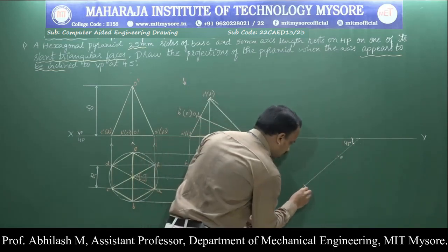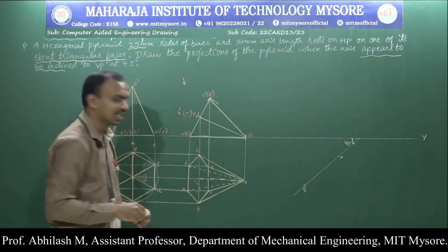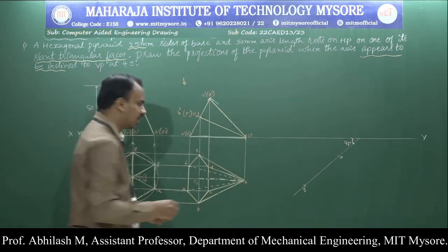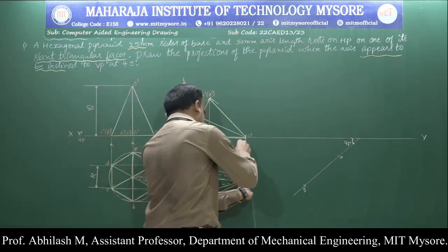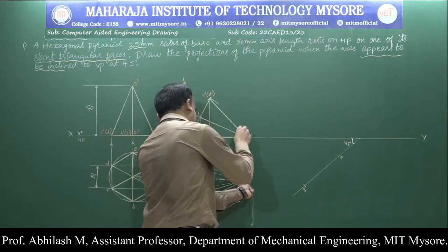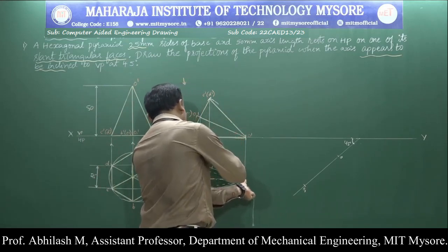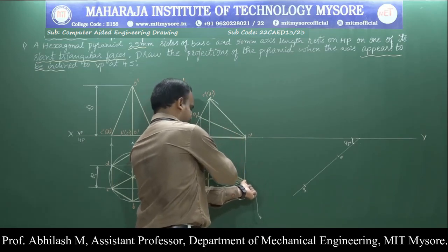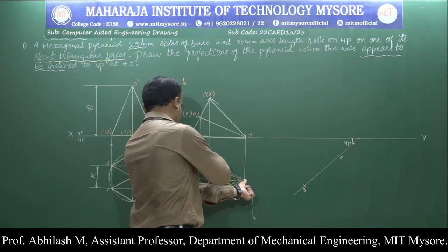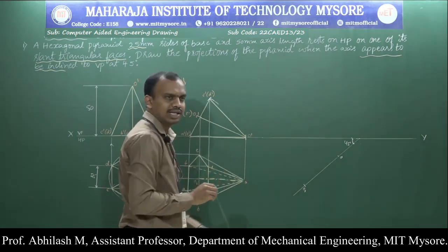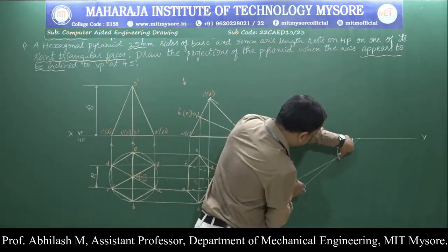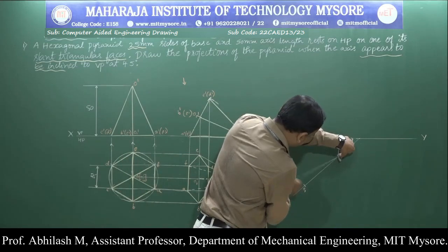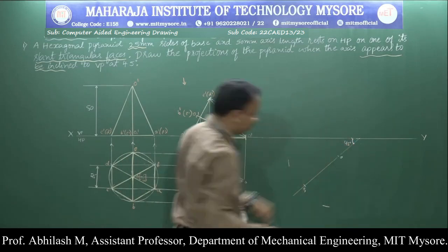So this is my O1. Now with the help of this, the rest of the procedure becomes simple. Measure from the sides. If you measure from only one side, it is enough because the other points will be the same. So O to E and O to B will be the same distance. If I measure from O to E, it is enough.